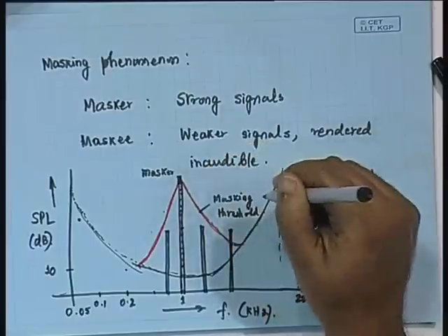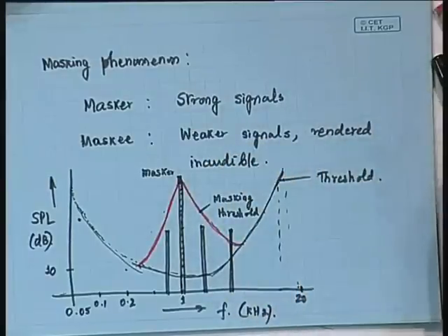So if you allocate your bits accordingly, whenever you are encoding an audio sample, you have to decide how many bits you are allocating to that sample. If you are having more bits, as you have seen, it is improving the quality; the rough figure is 6 dB for every extra bit of allocation.